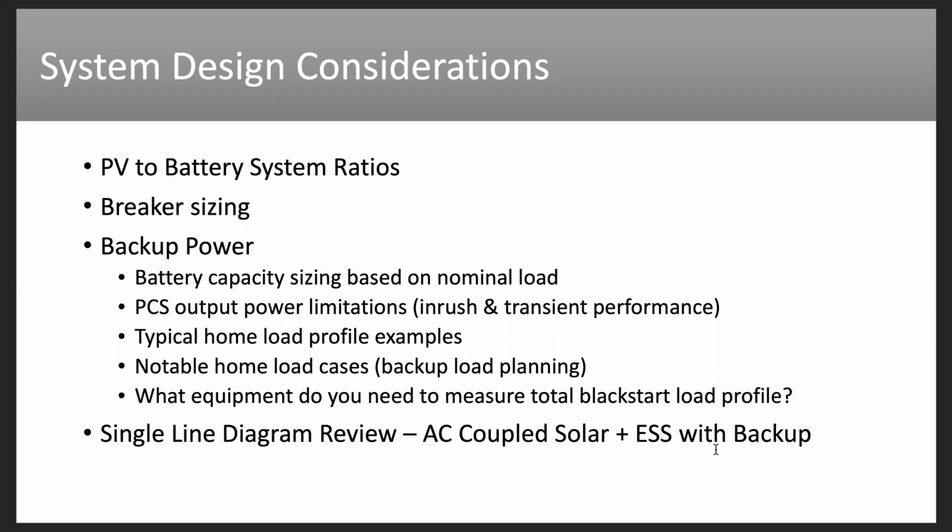We'll look at typical home load profile examples, as well as some notable home load cases, which will help for backup load planning. And we'll also be looking at what type of equipment you'd need to measure total black start load profile and a single line diagram review of AC coupled solar plus energy storage system with backup.